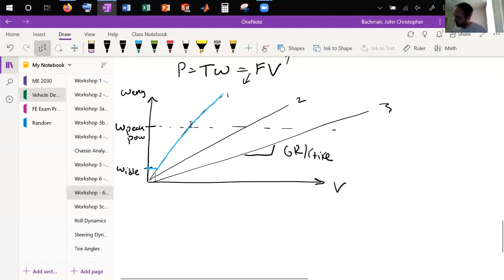And so right when you hit here, you don't wanna drop down here, because then you're operating not around peak power, you're operating way below it. So you come up here, maybe that's a little bit too high. Maybe you'd probably actually drop a little closer to here, right? So you might, typically the power band's flatter below the peak power, right? So you actually typically will stay a little bit on the low end.